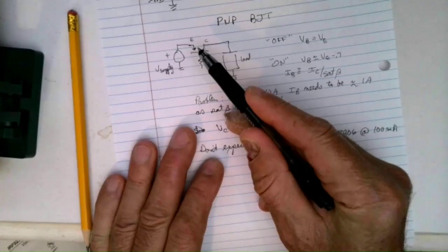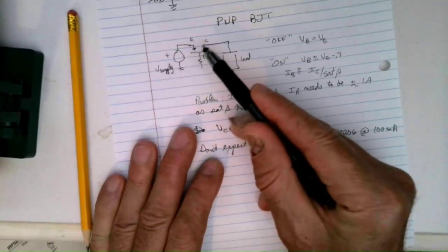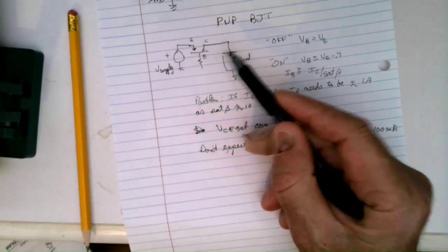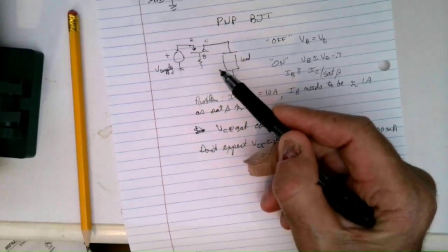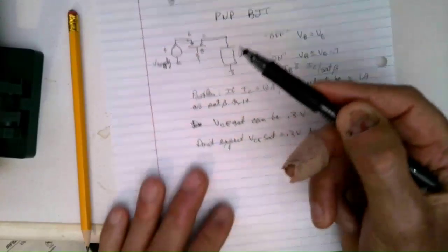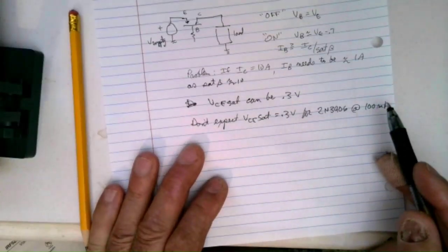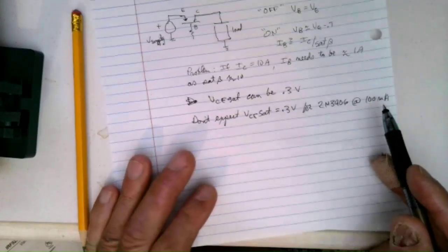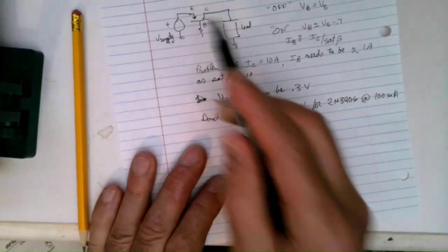They're pretty fragile, and if you put a fuse back here, the fuse won't blow fast enough to protect the device in most cases. And if you try to current protect these things, that can get quite complicated. So I think that says enough about the PNP BJT as a high side switch.